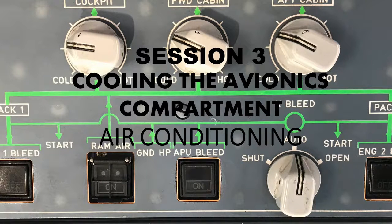So it's going to give a warning message, because all these signals are going to the computer, and then that's going to send signals to the cockpit with the warning messages of vent blower fault, which is one of them, or if it's an extract issue, it's going to be vent extract fault. And this is all when there's a decreasing pressure airflow that's detected by those switches. Okay.